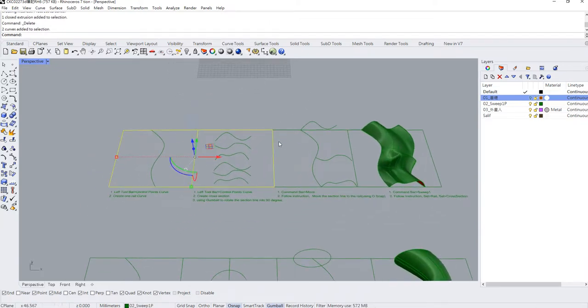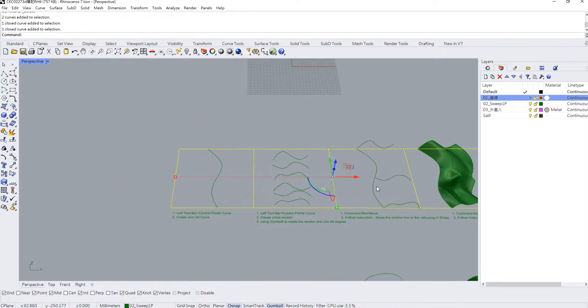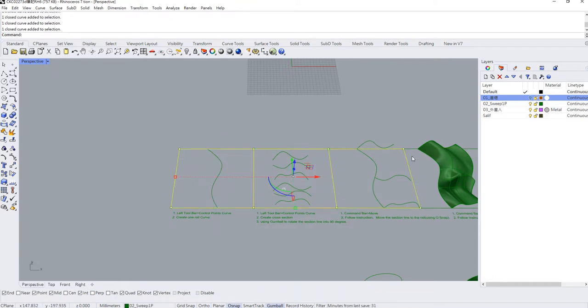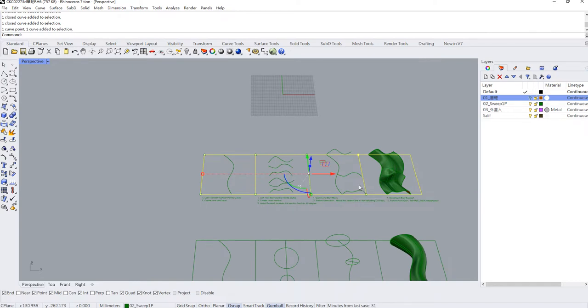Let's copy all these operating frames to the right. So select all of them, hold on your shift key, you can do multiple selections. And hold on your Alt key, you can copy these things to the right side. Sorry for that because probably I didn't select correctly. So let's do that again.